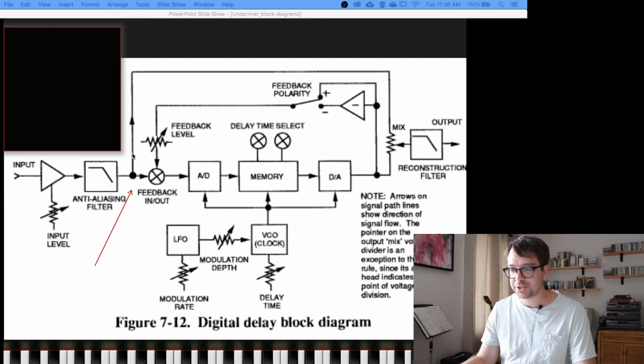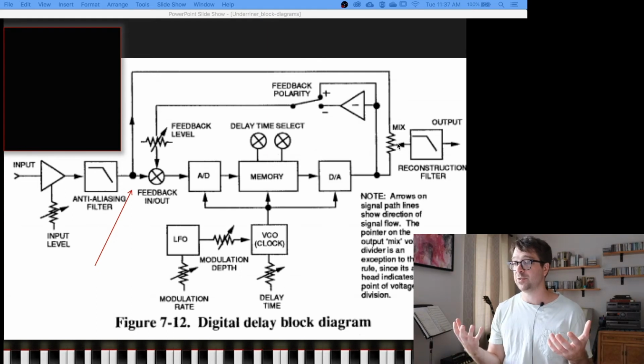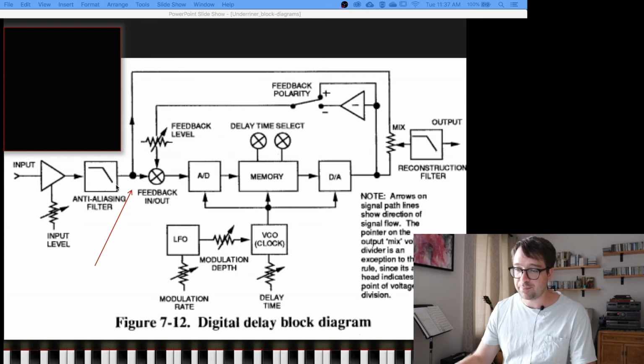We have a switch. Actually, sorry, not a switch. We have a split where part of the signal goes up here to the top to this resistor that's labeled mix. And then part of it goes to this whole bottom section and then to mix. So this section up here is just the bypass. That's the dry signal that's not being delayed or not being affected. This bottom half, so first of all, we go through an amplifier that's controlled by a variable resistor.